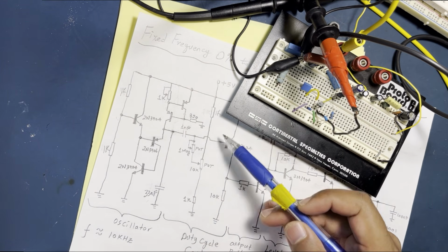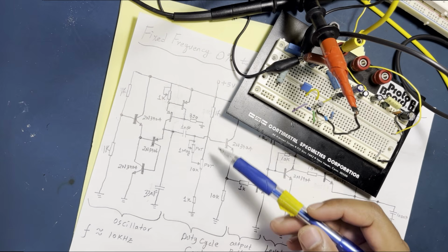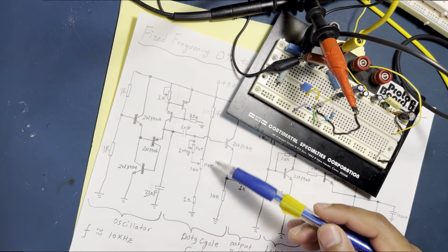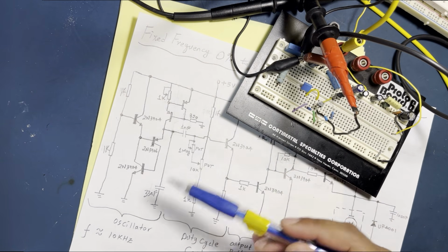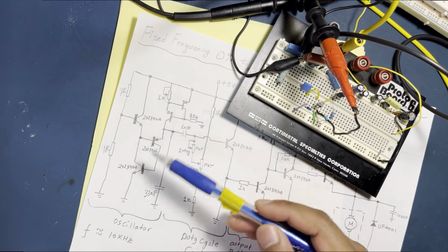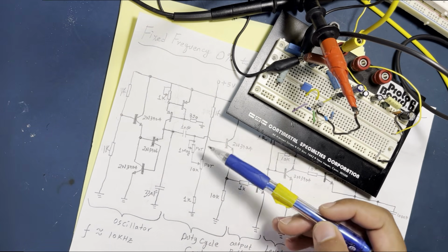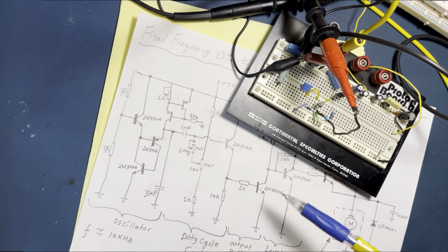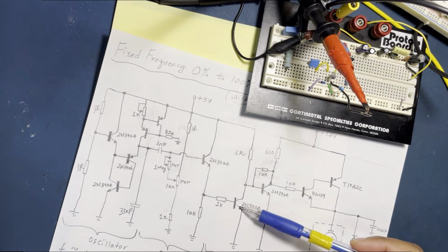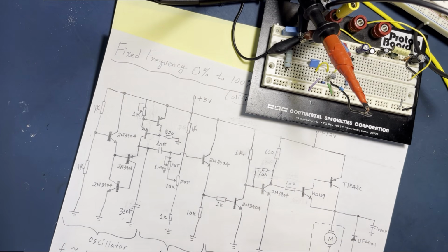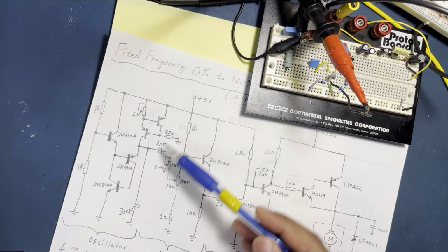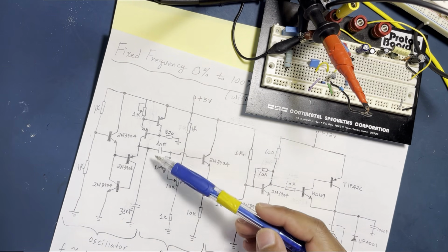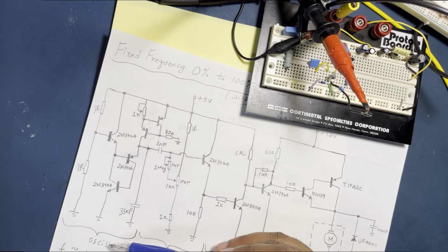And if there's time, then we'll just quickly talk about the duty cycle control. It's simply a resistor divider, shown here, which introduces an offset to the generated ramp voltage. That way, the ramp voltage gets a DC offset, which allows one of these switching transistors here to output a certain width of the waveform. But for now, we'll just quickly go over, in detail, the design of the oscillator, and we'll go from there.